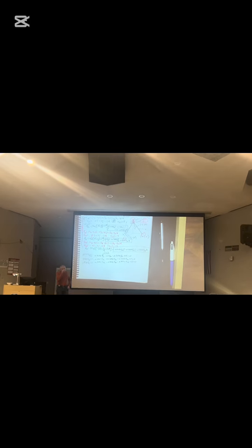Sum of forces in the Z equals 0, positive straight up. Put your K's: minus 0.9231 FPC minus 0.9231 FPA minus 0.9231 FPB minus 12 equals 0. Those 4, 5, and 12 are the implied loads.